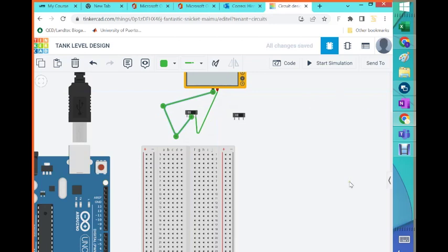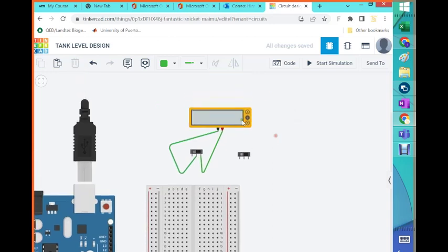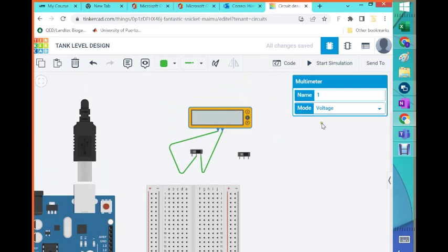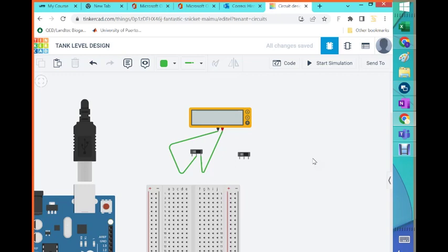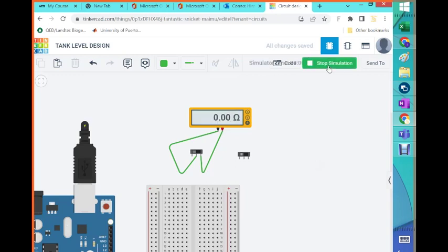A switch without a battery or anything, the only thing this instrument can read is what? If there's no battery, there's nothing. Resistance. That's it. Change it from voltage to resistance. Now, let's do the simulation. Start simulation. See? It went through and is reading megaohms, meaning that that switch is open.